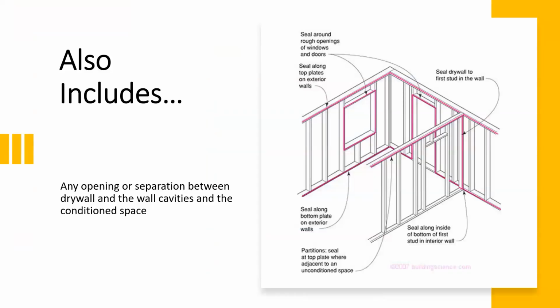The air barrier also includes, when you have the attic area and then you're looking at a home, anything in the attic, now you're going to have sheetrock or drywall separating that. That becomes your interior air barrier on the separation from the attic unconditioned spaces and the home. So with that, all those need to be sealed.